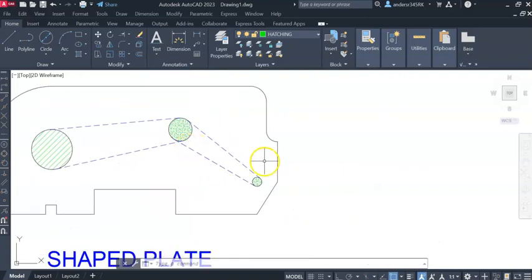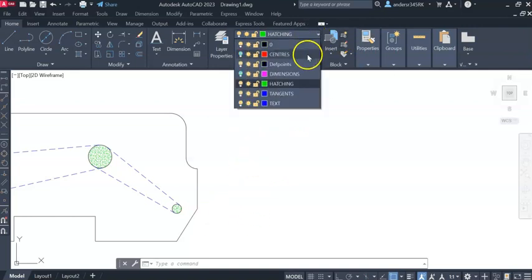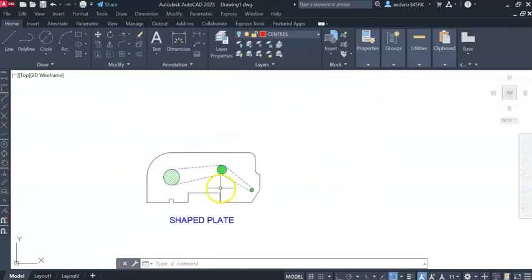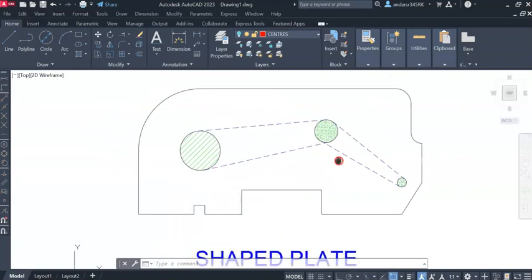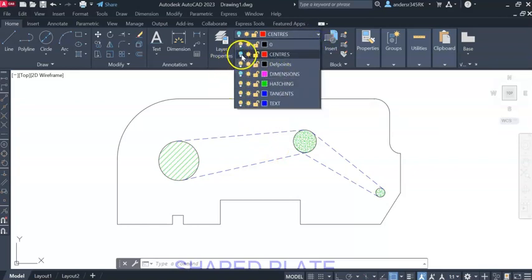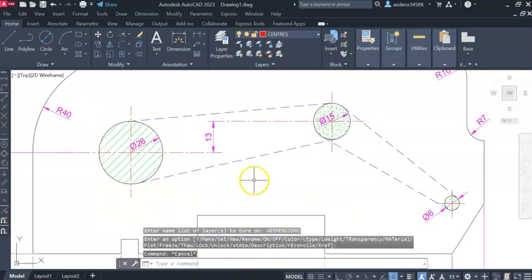Okay. If, for example, you want to put a hatch in an area, let's say like a portion of earth. If I go to plate, go to layer 0. Oh, sorry, I forgot to turn the layer on. Okay. Right. So when we're done, I almost forgot this. When you're done with the hatching and you're happy with it, you can go back and turn your layers all back on like you're supposed to. It's telling me that. So I'm turning it on, escape out of there to clear all of that, and there we go. It's just looking great. Okay. So now you can turn the layers back on after you've done all of that.